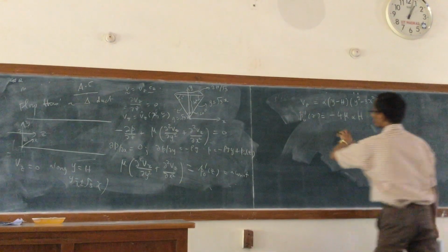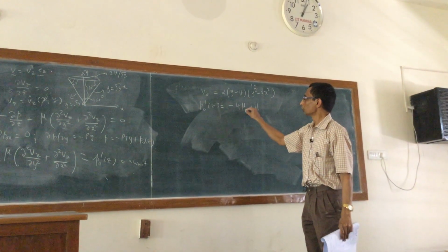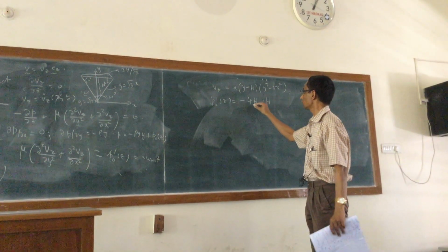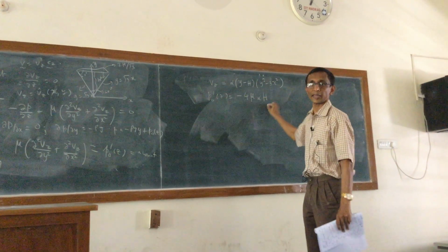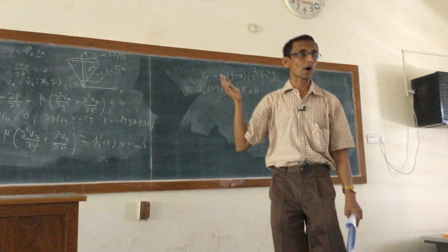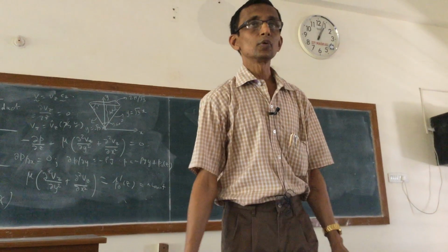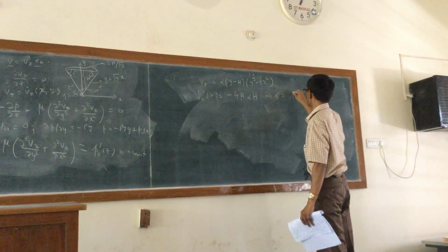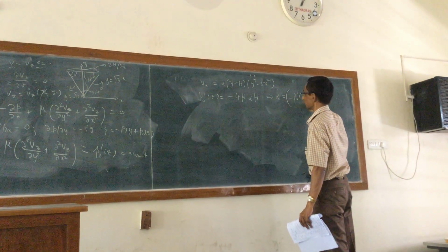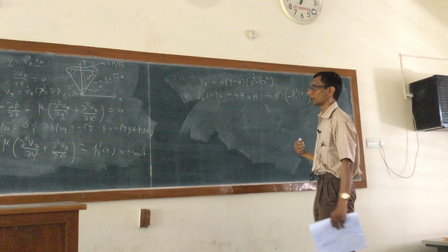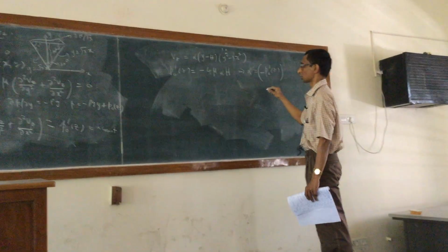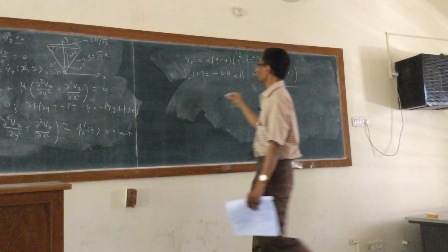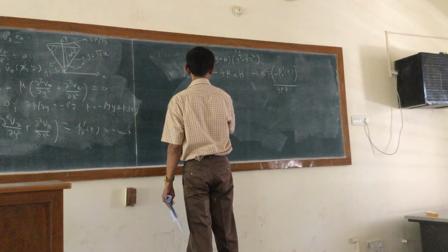If you substitute it in, then you will get mu times d squared Vz by dx squared plus d squared Vz by dy squared to be equal to minus 4 mu alpha h. You can easily verify that. That's clearly a constant. The alpha is a constant, mu and h are also constants, right? So from which I can calculate alpha now to be P naught prime of Z, that means the negative of the pressure gradient in the Z direction, that will drive the flow, divided by 4h.